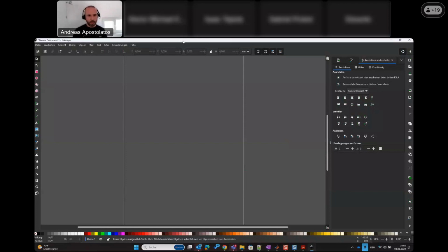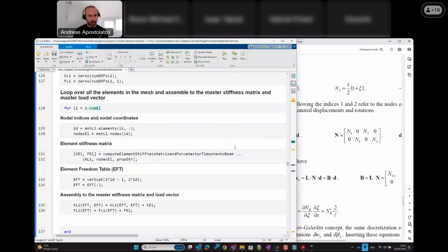Great. Okay, so we talked about the integration, about the parametric description, about the element parametrization. I hope it's clear that we do not perform any coordinate transformation here. It's not like in Finite Element Methods 1 with the traces. Here, we have one coordinate system, but two spaces. There's a difference between a space and a coordinate system, right? I hope that's not very confusing. So in this case, we have a parametrization because we parameterize our element constituents, like displacements or rotations or whatever you want, in terms of the parametric space of the element.